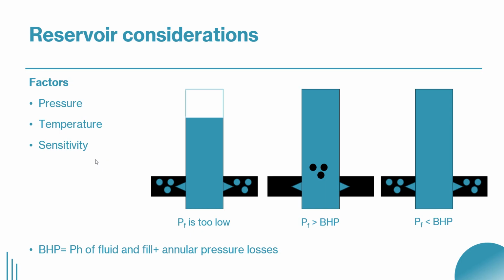The third point is sensitivity. For example, some formations are sensitive to fresh water, which will cause clay swelling. So in this case, you must inhibit your treatment fluid to avoid damaging the formation. And some fluids can cause emulsion or scale with the formation fluid. So always consider the sensitivity of the formation and the formation fluids to avoid damage to the formation and the formation of emulsion and scale. So these were the factors of reservoir consideration during fill removal operation.